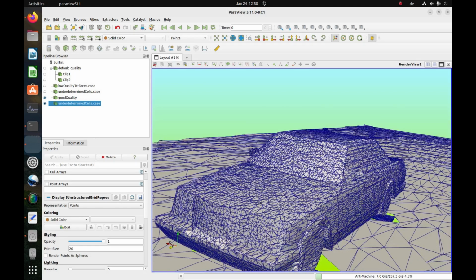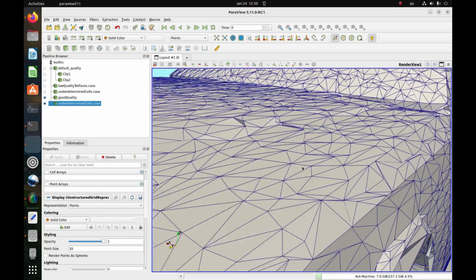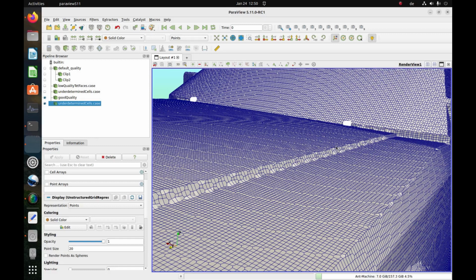What I can also mention here, each time when you want to create a mesh with good quality, you have to choose between good quality or best quality and between best geometry reproduction, so that every edge in Snappy is exactly the same as the edge of the STL file.